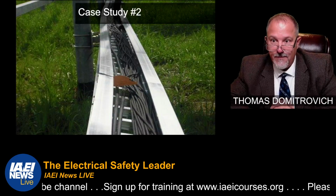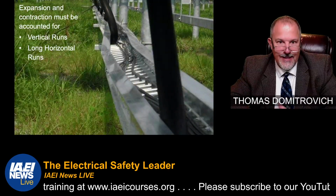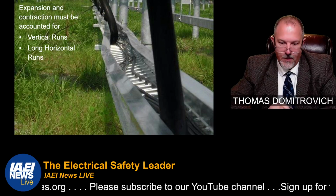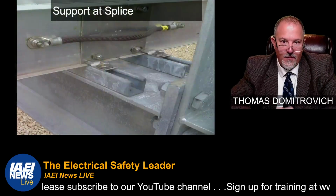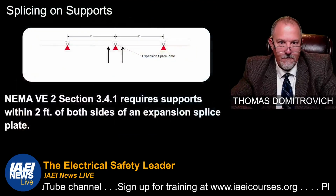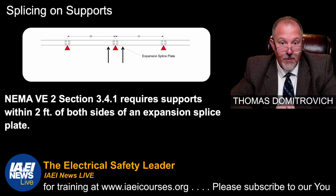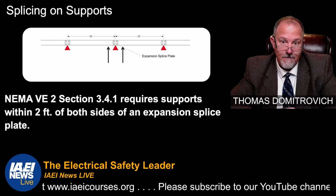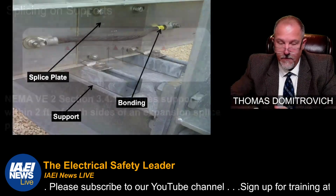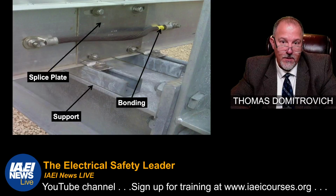Here's another little case study. Look at this puppy. That doesn't look good. It can't be good, right? Look at this, huh? Expansion and contraction were misaccounted for in vertical runs and long horizontal runs. And we saw one of these before, support at the splice plate, right? NEMA VE 2 section 341 requires supports within 2 foot of both sides of an expansion splice plate. And that's not what they did.